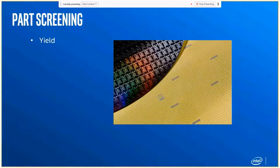Even FPGA is one approach, and then what was the other one? Palladium. Palladium is another one, right? It looks like washing machine size boxes. So you can use that also. There are different ways of doing this, right? But from a higher level, you have RTL where you are just doing register read write. Is this gate going up? That clock coming down? That kind of thing. Emulation is where you are faithfully mimicking the device, but at a very slow speed and so forth. Then you have the software simulator where it's got nothing to do with RTL, but it helps the customers get going with the application.